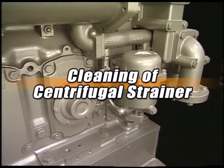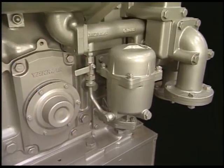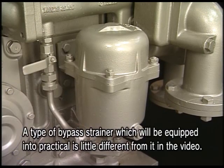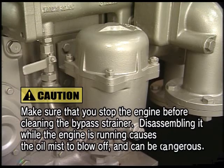I will explain the procedure for cleaning the lubricant oil bypass strainer, which is to be done about once a week. This centrifugal bypass strainer is very effective to control the increase of lube oil contamination during the engine operation. During the engine operation, always open the inlet valve of the bypass strainer to flow the oil through it. It is important to clean it frequently in order to sustain the effect.